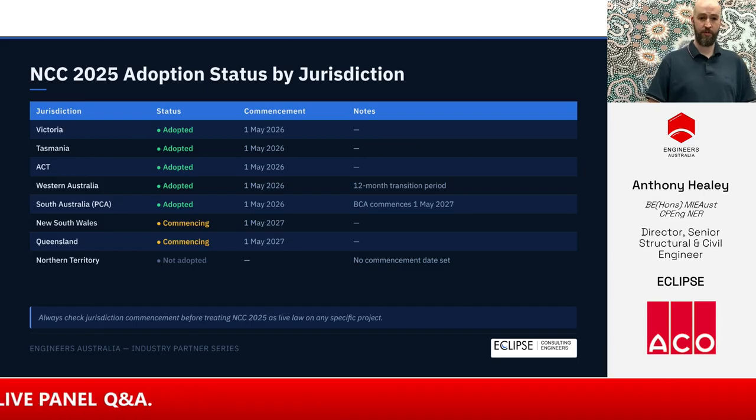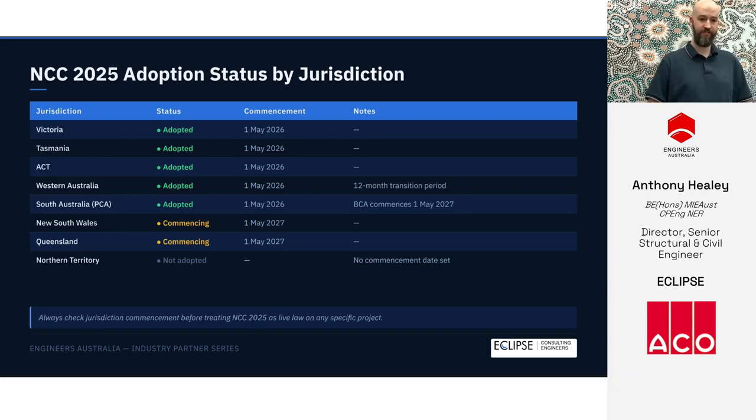The bottom line is always check jurisdiction commencement before treating the NCC 2025 as live law on a specific project. Transitional arrangements also apply in some states. That said, it is worth designing to the 2025 framework now, particularly for overflow design, where it provides clearer DTS support than the previous edition.